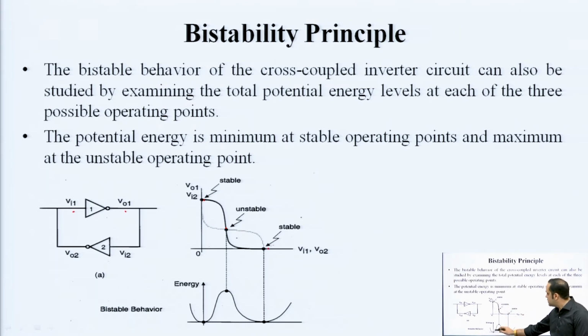If you see the potential energy graph, the energy at point C is quite high. Circuits tend to reside at a low energy state, that is the preference. Lower energy states are usually occupied earlier. And even if a circuit is at a high energy state, it tends to shift back to a lower energy state. So, a circuit biased at point C will either shift to point A or point B, resulting in a stable operation.